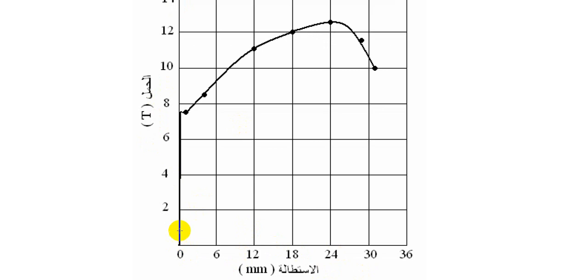The linear elastic curve extends from the point of origin, at which the load and extension intersect, until it reaches a value of 7.9 or 7.8, the upper limit, the value which constitutes the peak of the elastic limit. Consider the peak of the elastic limit exactly at this point, 7.8, and the upper yield point.